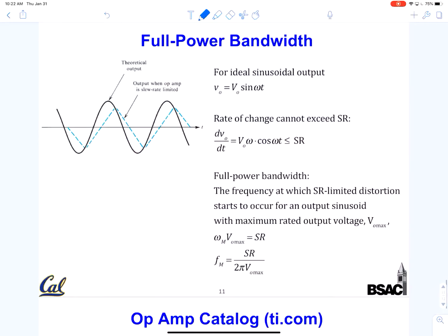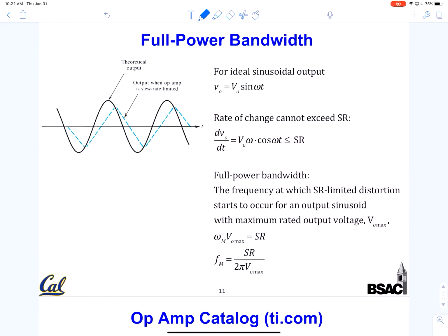There are some signs on the oscilloscope. If you have a sinusoidal input voltage, ideally you have a sinusoidal output, shown as this blue curve here. This is the ideal case. Now, if you see a distortion like this one, it's a typical signature of slew rate limit. The waveform departed from a sinusoidal waveform. Here, for example, the ideal slope is too high, higher than your slew rate.